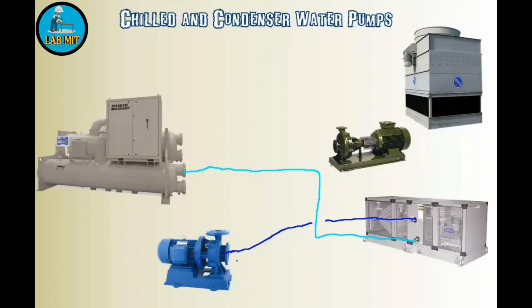And in case you're not familiar with pumps, if you looked at this type of pump here, the inlet is actually going to be this horizontal part here. And there's an impeller in here, so you can imagine it like a boat propeller, but this is an impeller, and it will actually draw the water into the center portion of it and then spin it around and shoot it out the top here. And this is going to go right back inside to the chiller.